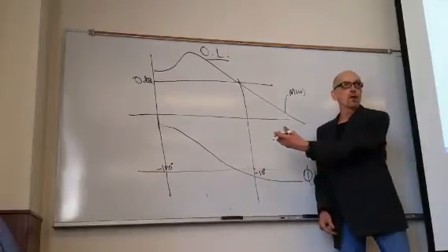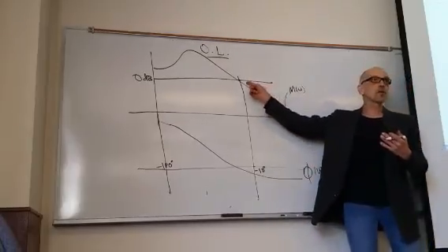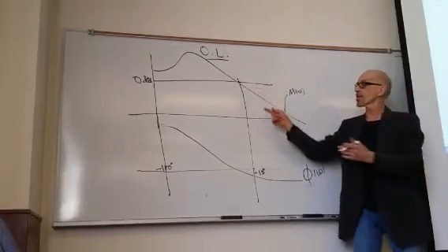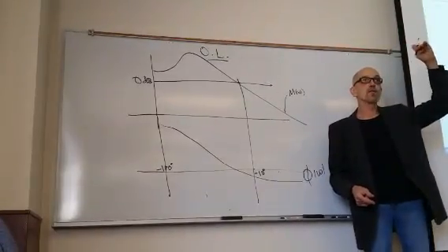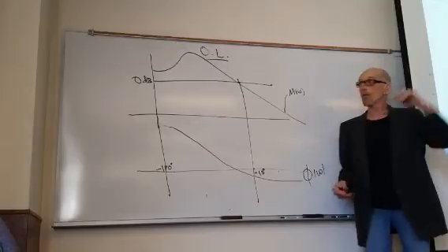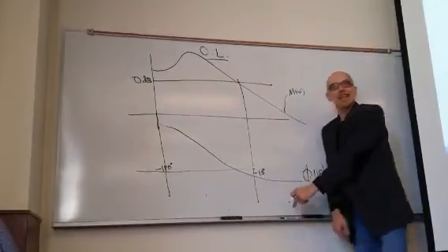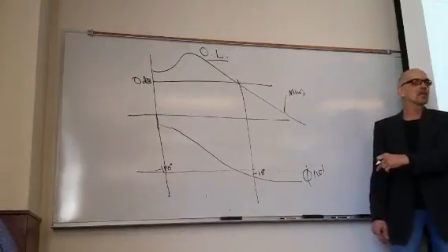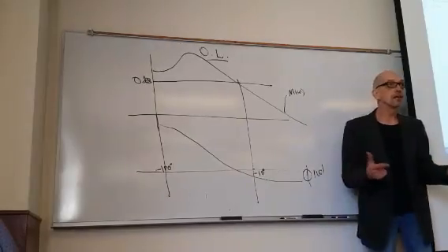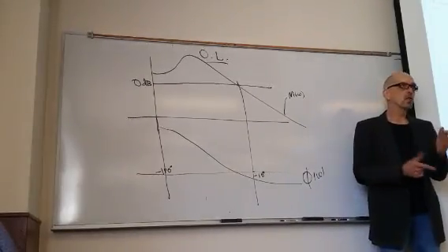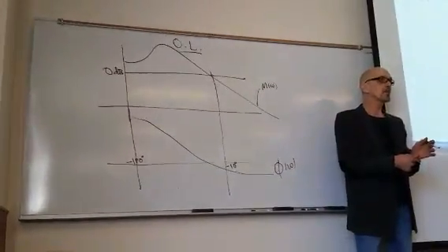Except I know that I'm going to be moving to the right with the crossover frequency, because remember that compensator, what it's going to do is at the maximum phase, that compensator adds alpha dB over 2. So this whole thing gets shifted up and the gain shifts over to the right where the phase is even less than negative 10. So you say, okay, I want 40 plus 5 or 10. That's the cushion that I talked about, right? Remember that? Am I going too fast here?